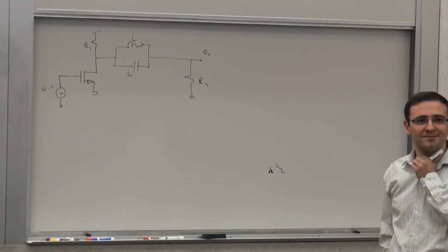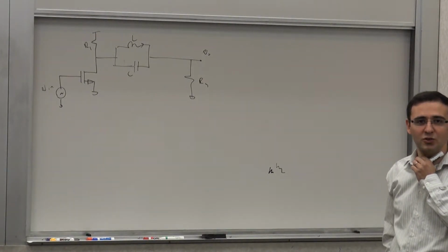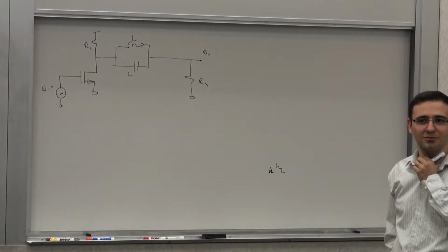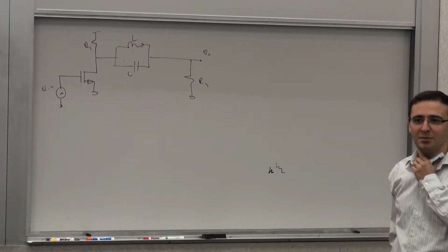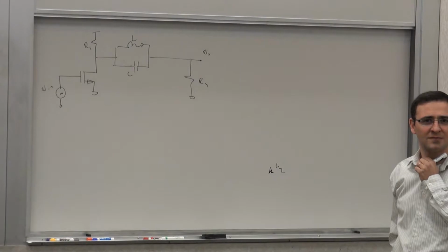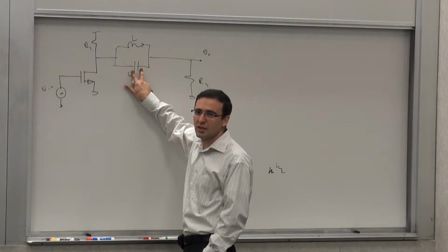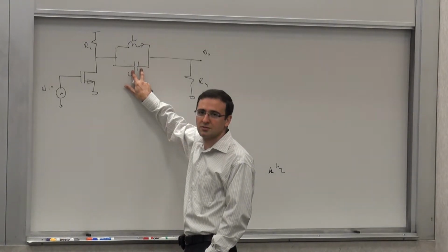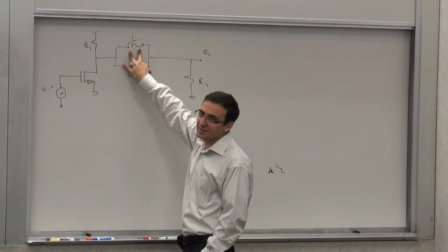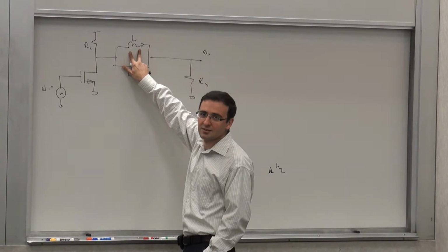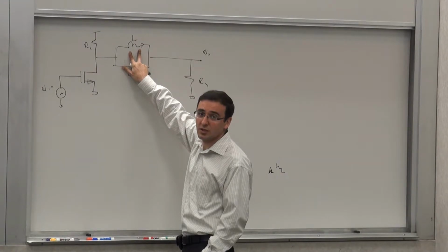Zeros. How many zeros? At this point, 2, 1, 0. How many people say 0 zeros? No zeros. How many people think 1 zero? Okay, let's look at it. If I short circuit this capacitor, would I get a non-zero transfer function? Yes? If I open circuit this inductor, do I get a non-zero transfer function?